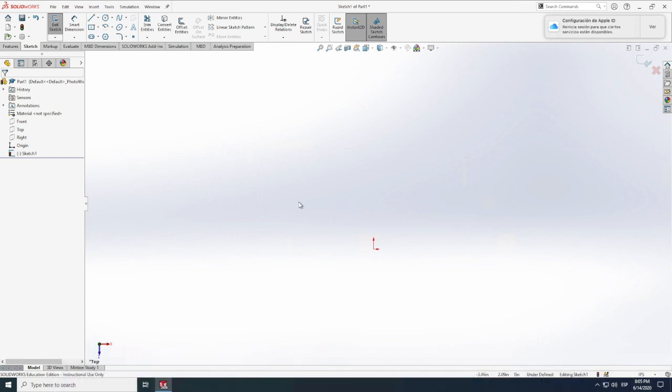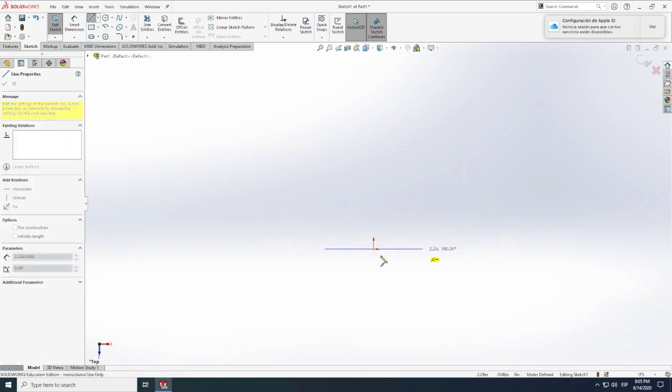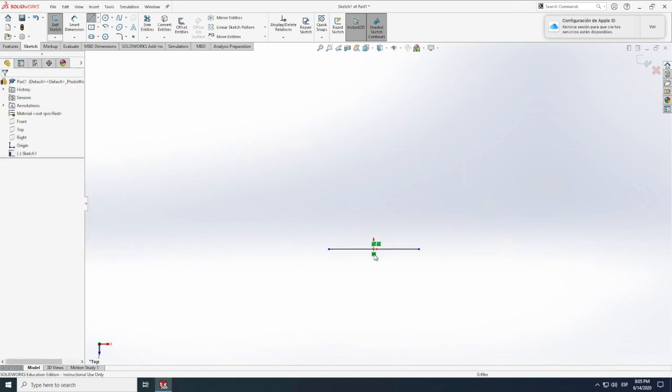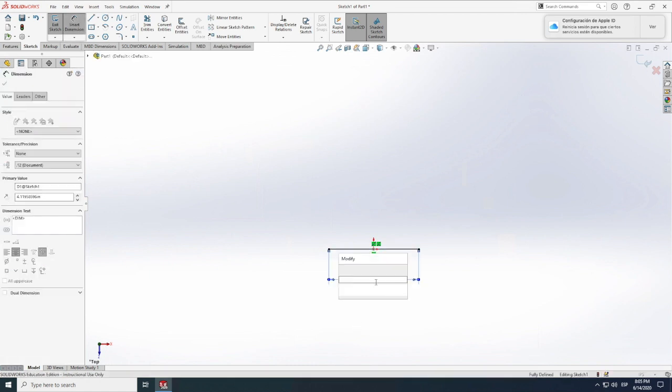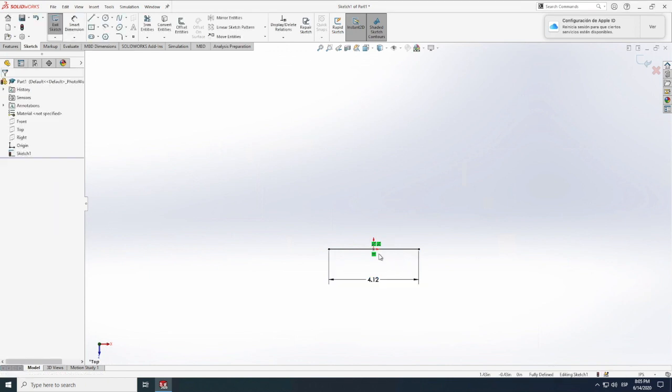So what we will do next is continue exploring the line feature. Before we go to center line, we go to midpoint line, which is essentially a similar thing. Let's click again in the origin and it draws the line, but it is symmetrical through the point that you have chosen. So it's still a single segment, but it has two equal sides. Let's define that as usual. So there you go. This will be handy for some applications.